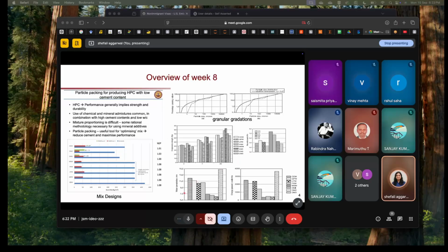And lastly, it is about the durability. In durability, 2 types of testing have been done. One is water permeability or water penetration. Second is RCPT, in which we calculate the charge passed, in coulombs. These 2 types of durability testing were done for the different 8 types of mixes.